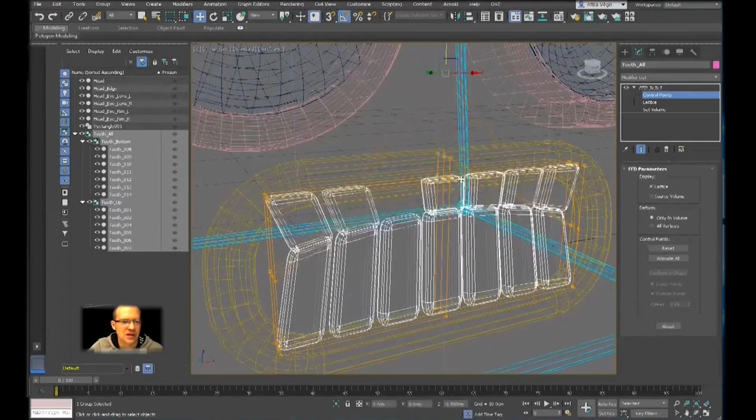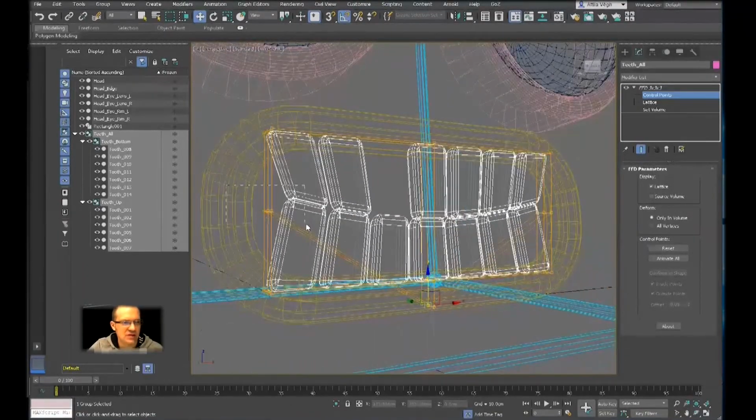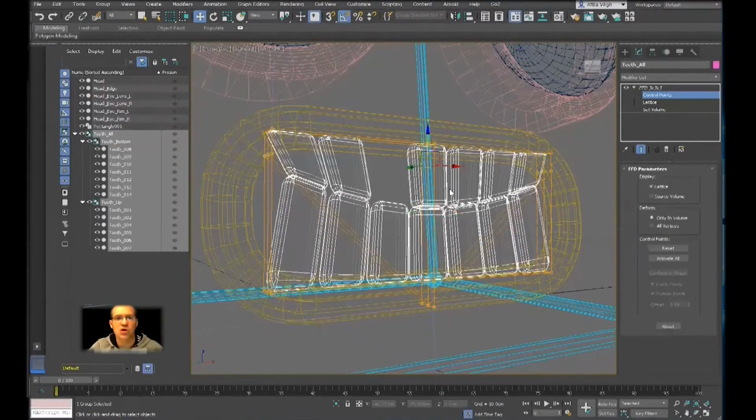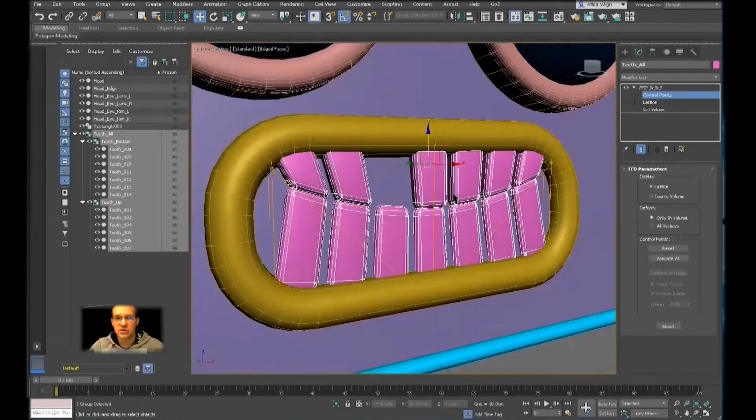But more than that, just let me put in a smile. I can select the sides, rectangular selection, holding on Control because I want to select the other side as well, symmetrically. There's no automatic symmetry here. So I'm holding on Control and selecting these as well. And I'm pulling this up a little bit to work on that small area. You can also scale, rotate, and move in every direction. So this FFD is flexible to make tiny corrections for yourself when you design something.